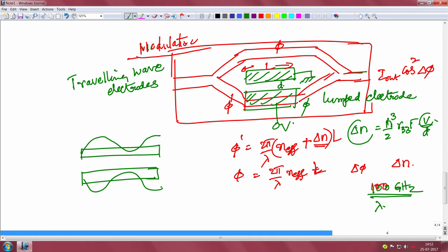In order to analyze these electrodes, you have to treat them as microstrip lines. These are effectively waveguides of microwave frequencies, where the microwave can be guided along these strips. Typically, you need to have a load and your source, a microwave source, at the other end. So, this is a microwave source of certain frequency, and the guided wavelength, and so the properties of these